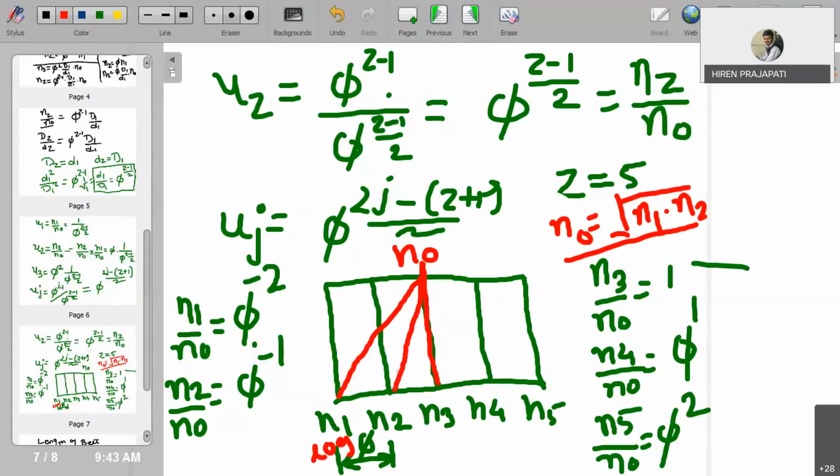which gives us n2. Now from n0 to n3, the third set of pulley is giving us the same speed, n0 to n3, as per this transmission ratio equation. Now as per this transmission ratio equation, n4 has a geometric progression of 5 to 1 with respect to n0. Then we draw a line here. Similarly, n5 is a 5 to 2 progression with respect to n0. So this is what we can say is the ray diagram of the cone pulley type of gearbox. I hope it is clear.